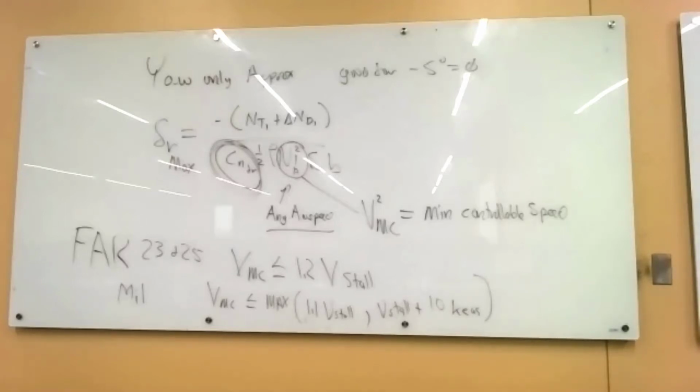So we have the 3x3 trim solution for one engine out, and then we have the approximation, so that's the second thing. But fundamentally, I want you to be able to explain to your husband or wife or spouse or boyfriend or girlfriend or kids or grandparents, I want you to be able to draw a picture and explain why one engine inoperative is a problem and why it's important and why the rudder is there. So that's where we talk through that you need the rudder to counteract the yaw from the engine. Then you get some side slip because the airplane pushes sideways, and then you need some aileron to counteract everything.